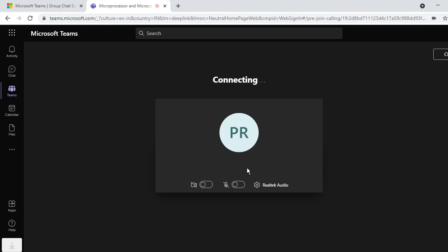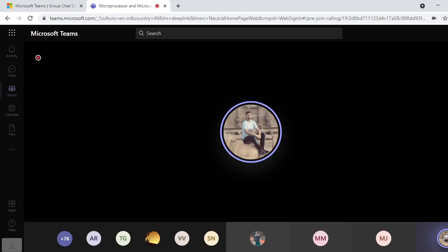Hence, this AD0 to AD15 will go through a high impedance state. Once the data has been transferred from the data bus onto this transceiver, once the data has been read or written from these externally interfaced memories, the next task is to put that data onto the transceiver, right?